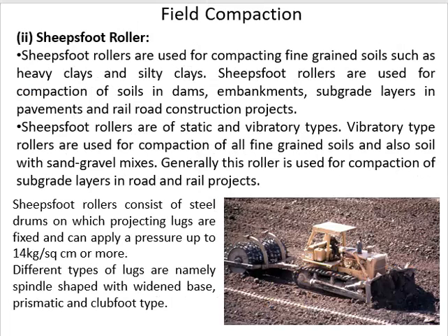Next one is sheep's foot roller. For compacting heavy clays and silty clays, sheep's foot rollers are effective. These rollers are employed in road and rail projects. They have projecting legs on the drums which provide kneading action. Sheep's foot rollers are of static and vibratory types.